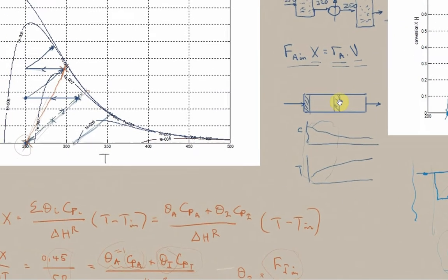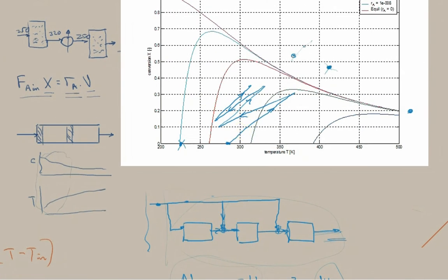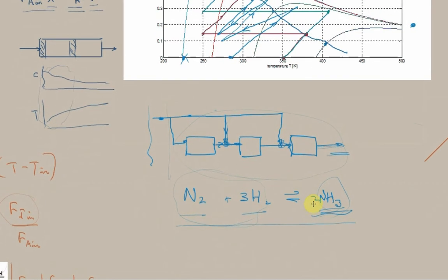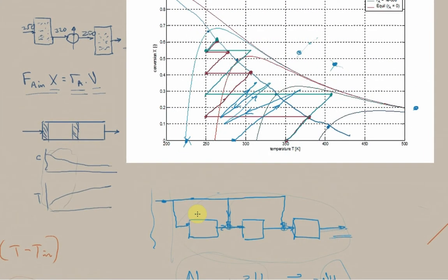So in the first cases, we had talked about, we had established a way to work with small reactor volumes. So this red line gives us very small reactor volumes. Green line gives us fewer reactors, but they will be larger. And the blue line, that's about easy to separate components, and we can address high flow rates and get away with small reactors. You can see we are staying generally closer to this high rate region.